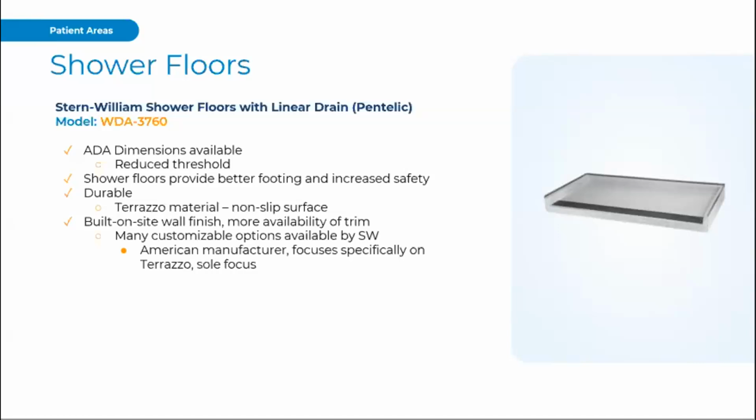But as a general guideline for OBC and the BC building code, we're looking to not have less than 1,500 millimeters, 59.1 inches wide by 900 millimeters deep, have a threshold level with the adjacent finished floor, or a beveled threshold not more than 13 millimeters higher than the adjacent finished floor. And in BC particularly, where it is higher than 6 millimeters, a bevel to a slope no steeper than 1:2. So there are some very unique parameters there that need to be kept an eye on.